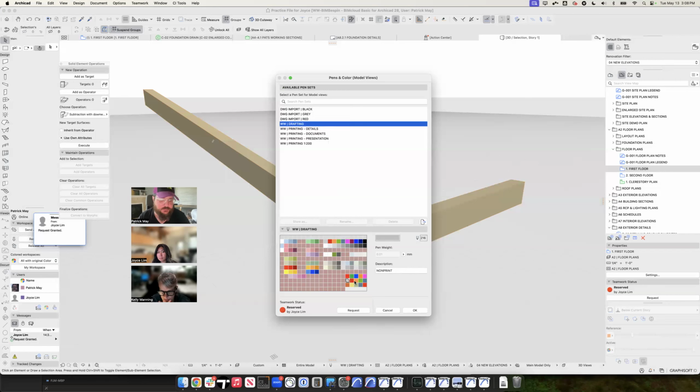What are those used for? They're not used, and they shouldn't be. The reason for that is because if you turn a pen white and that pen is going over the top of something else, it just masks that thing out. There's no such thing as non-print in ArchiCAD. Non-print is the layers off, basically, or the elements otherwise not visible. But somebody made the request, and it ended up in the template, and it's just been hanging on.